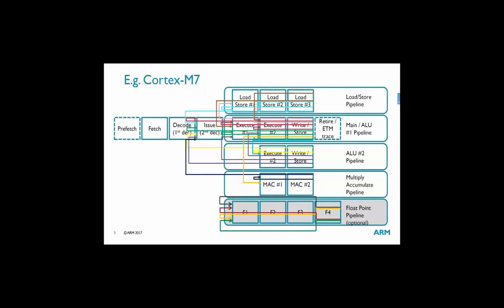And if you can imagine trying to verify this, you have to verify every possible sequence of instructions that can activate every possible sequence of functional units, forwarding to every other possible sequence of instructions, activating every sequence of functional units. So to do this exhaustively is extremely difficult. The state space explosion happens very, very early, very quick. And for a simulation verification methodology, where you have to write your stimulus, you have to think of all the corner cases ahead of time, all the different instruction sequences that you need to hit, and this is very difficult.